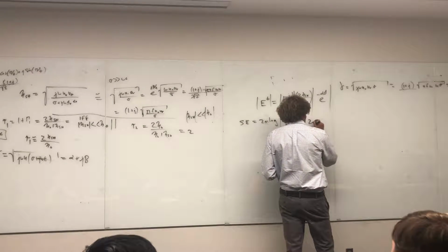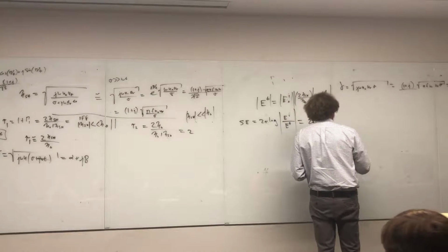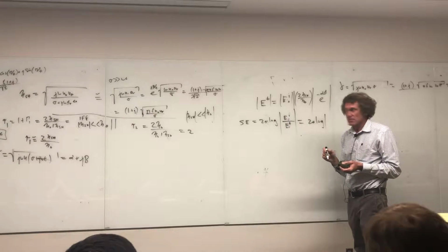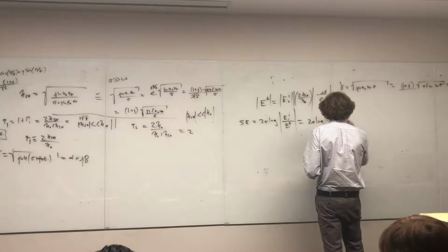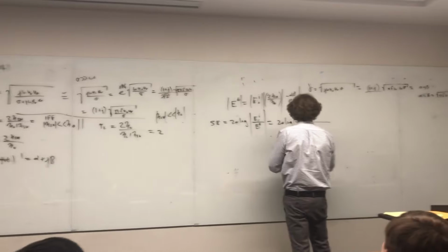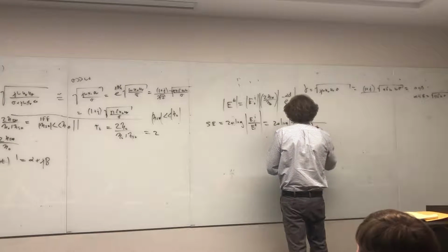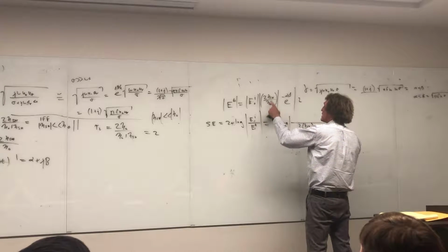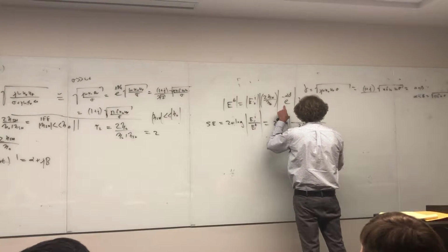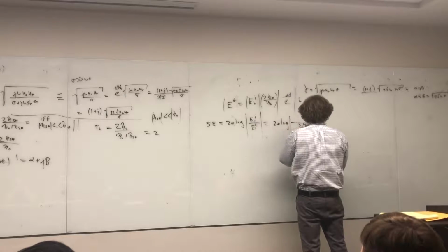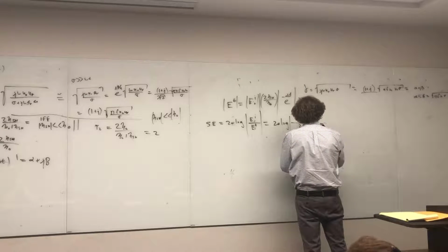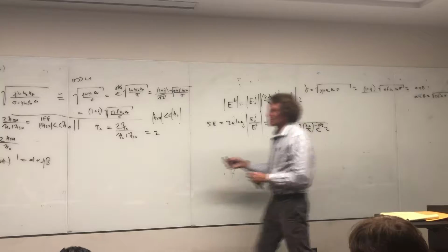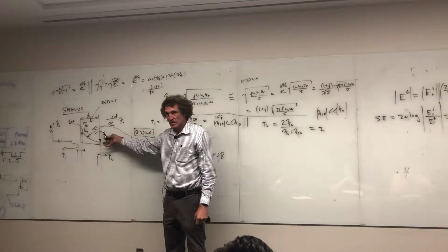So if you put in the numbers here, 20 times the log of the magnitude, you can see right away that the E naught incident here will cancel this E naught incident, and the transmitted field. Those go away, so I'm left with 20 times the log of 1 over this. So it's going to be 2 downstairs, and then it's eta shield over eta naught. And then I got to actually multiply that by 2 again. That's actually going to be the transmission coefficient tau 1. Then it's times e to the minus alpha d, or really, I'm just going to put this as simply d over the skin depth. So it's e to the minus d over the skin depth. And then it's going to be times 2 because, remember, the transmission coefficient right here is just 2 for a shield. This almost always is the way it is.